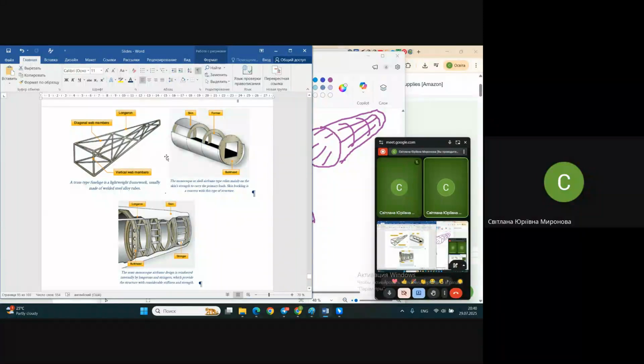Quite clear that these beam-like structures should be used when you have skin material which is able to keep the shape. And why did truss-like structures appear first originally? Just because people at the beginning of the aviation era had no appropriate materials, convenient for constructing those structures with the necessary shapes.